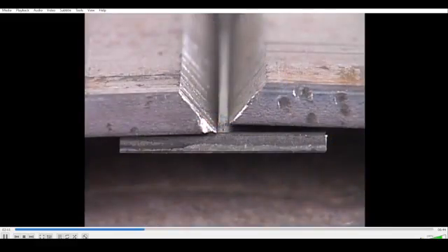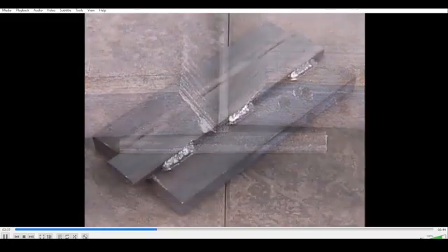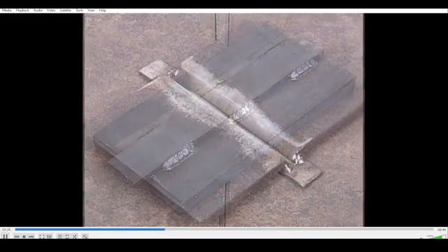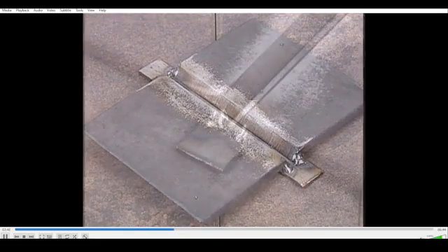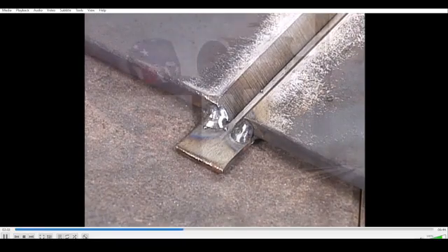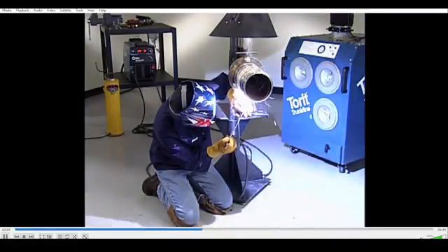Next, the joint preparation is examined, and the surface condition of the material is checked for proper cleaning and lack of flaws. Poor fit-up, contaminated base metal surfaces, improper equipment and settings can lead to weld discontinuities or defects. If backing is specified, it should be in accordance with job specifications and securely fastened in its proper location. Verify that the tack welding procedure and the tack welder qualifications meet the code or standards requirement. Tack welds must be checked closely since they become part of the finished weld and should meet the same soundness requirements. Pre-weld visual inspection also includes examining the equipment, power sources, fixtures, clamps, and so forth to ensure proper operating condition.